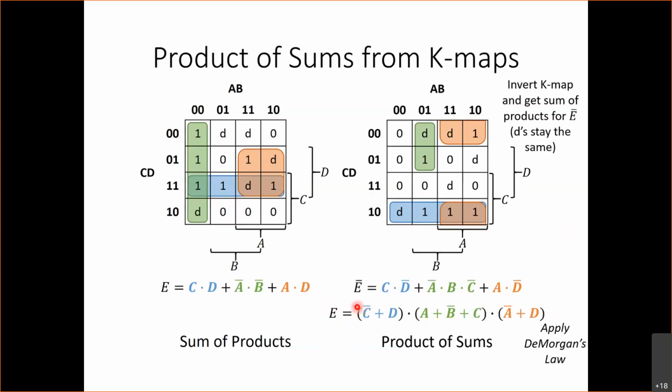You guys are observing that the one on the left is more efficient, and that's correct. In this case, I need a 2 input AND gate, and a 2 input AND gate, and a 2 input AND gate. That's 6 inputs in total. And then I need a 3 input OR gate. That's 9 inputs. And then I need 2 inverters. So that's 11 gate inputs in total.